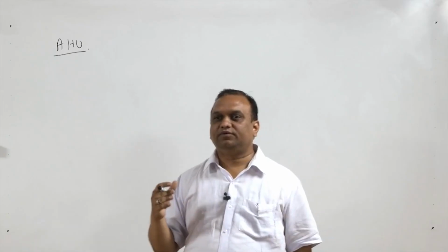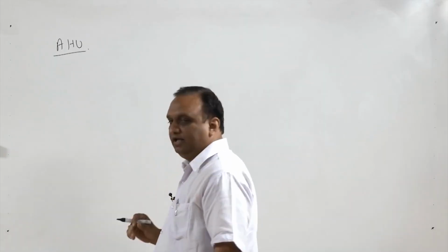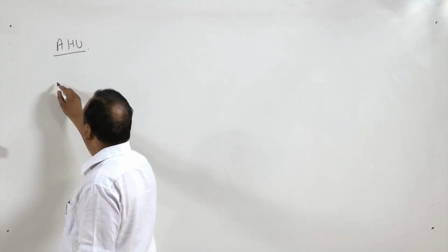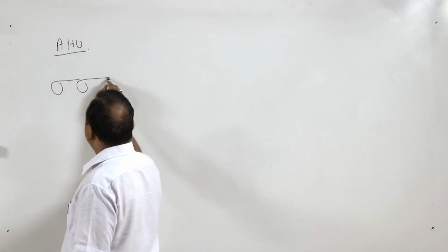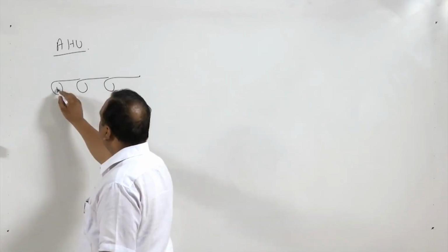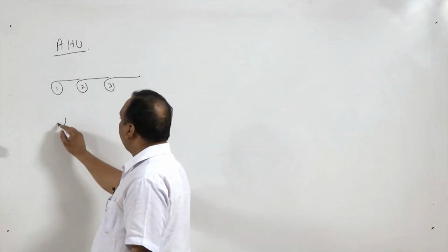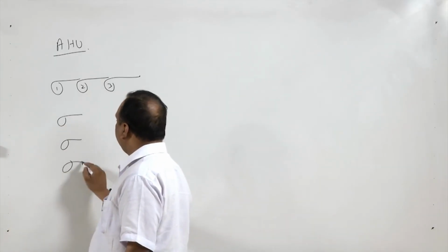It can be a single fan or a bank of fans, and fans can be connected in series. Suppose very high pressure is required, then fans will be connected in series. If high flow is required, then fans will be connected in parallel.